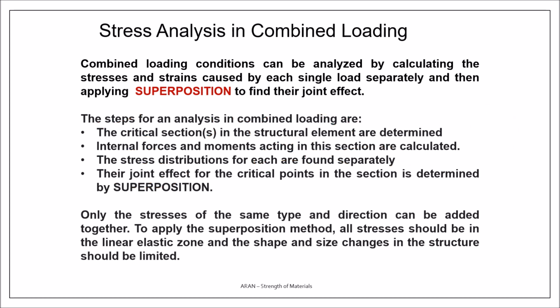When you want to superpose stresses, you can only add the same type and stress in the same direction. So you cannot add a normal with a shear stress, or stresses in different directions. We have to consider this during the superposition. We also have to be sure that we are still in the linear elastic zone and that the shape and size changes in the structure are limited.